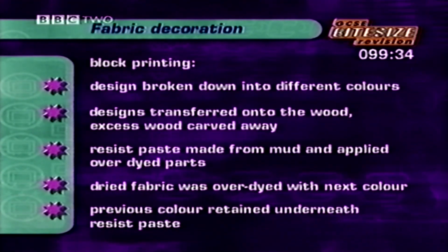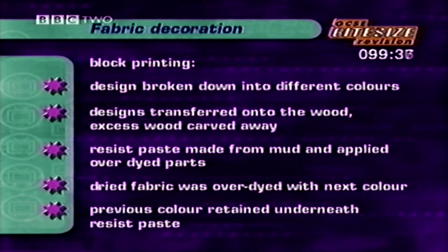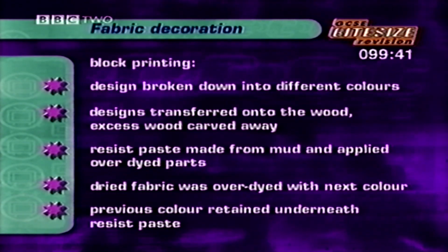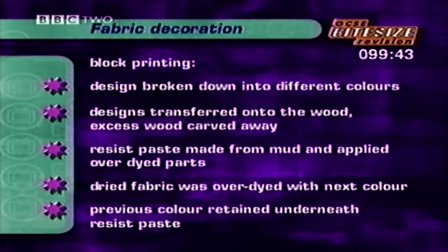Of course, you don't need to use teak to make the block. Foam rubber board or even polystyrene can be shaped to produce a printing block, and the same techniques of marking out your pattern and carving apply.